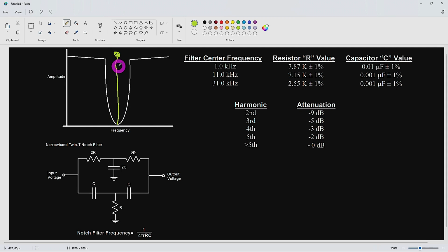This fundamental signal is huge, but the harmonics are really tiny. So what we want to do is make sure that this gets attenuated as much as possible so that the instrument we use can be used to measure the harmonics alone. And then since we know what signal we are putting in, we can do a relative measurement, basically do 2 measurements in order to get a THD. It's a very simple idea.